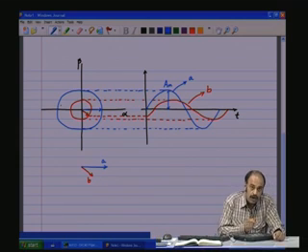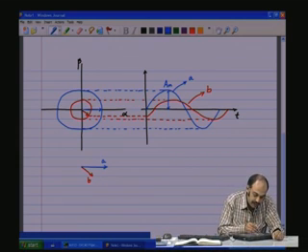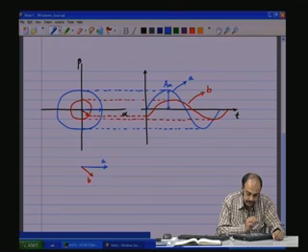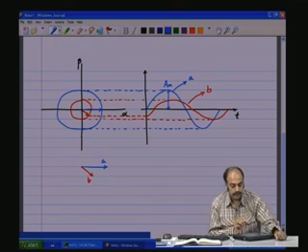Or in other words, if we have a space vector like blue and a space vector like this red as shown here with the space difference, and then if they rotate at some given frequency, both rotating at the same frequency, then on projecting onto the temporal coordinate system, they will evolve into the sine waves as shown here, where the red sine wave is lagging the blue sine wave. So, which means the red phasor here is lagging the blue phasor. This is the meaning of this particular thing.